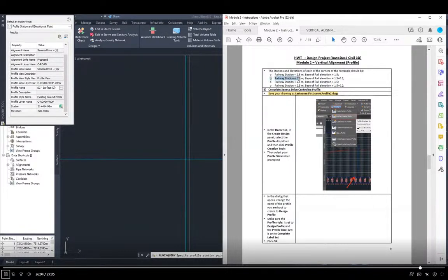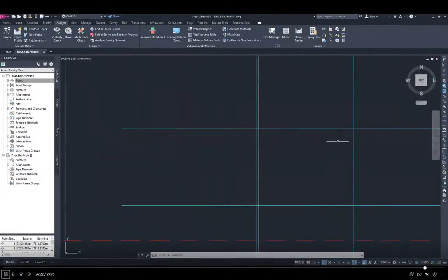Let me highlight it, right? And the base of rail elevation up, that minimum 1.5 plus that extra 0.2. And your 4 points are all reflected in one of these 4. So you can do a little checking of your calculations to make sure that you place these points right. I know that they are correct on mine.